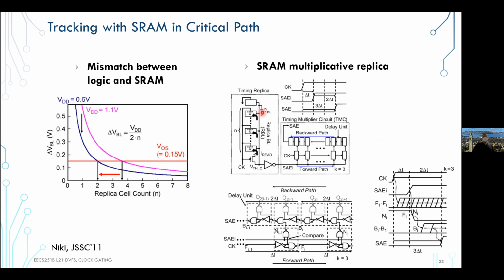So if you have here an event that discharges too fast and you want to give yourself more time, you essentially configure this delay multiplication circuit. So you add a factor of, let's say, 3. That way you don't have to change the number of cells that are discharging, because the more cells you have here, the stronger the current is, so the less noise in that one unit timing estimate you have. But then you have to multiply up that delay because it may be too fast. Right? That's just one example of how people do it.